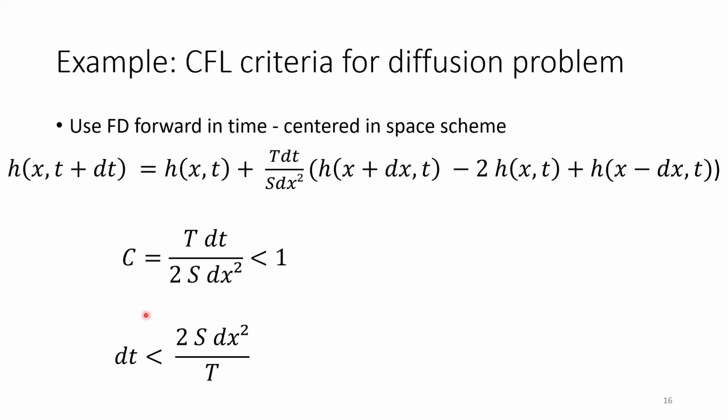Right, so you can analytically derive this CFL criteria. Don't worry, you usually don't need to do this if you use some kind of commercial program, because most commercial programs will use implicit time stepping anyway. But if they're not, even then, the time step will be calculated for you to make sure that you fit this criteria, because the maximum allowed time step depends on your discretization scheme.